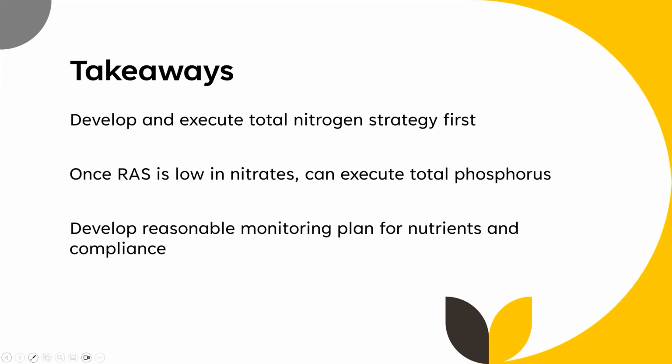With nutrient optimization, you're going to need to add a couple additional parameters to that. Most likely going to be looking at orthophosphate at a couple of places in your facility, and possibly also looking at nitrates at some places in your facility. Each facility, again, is going to be quite different there.